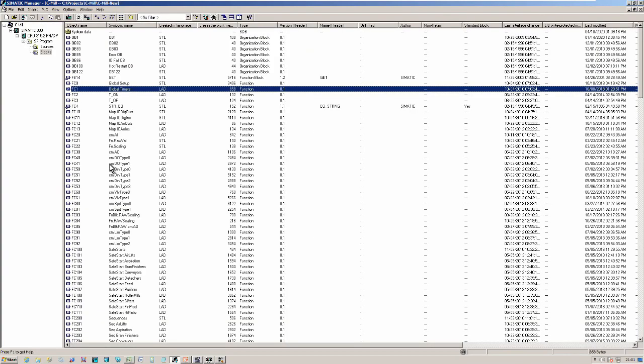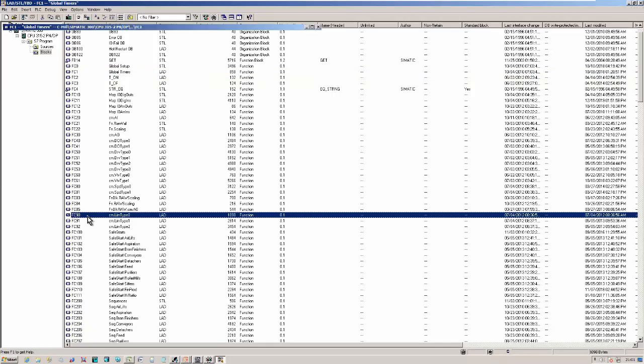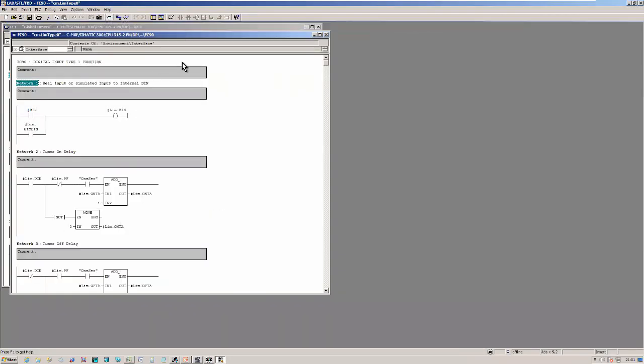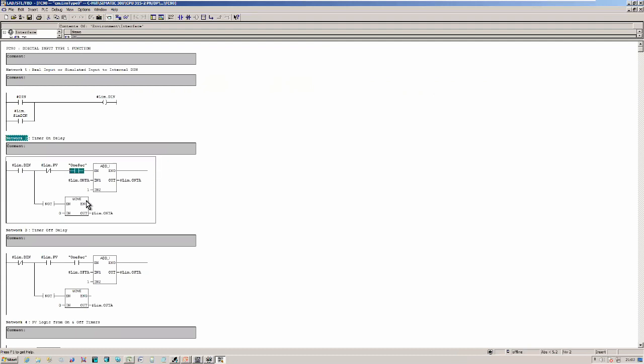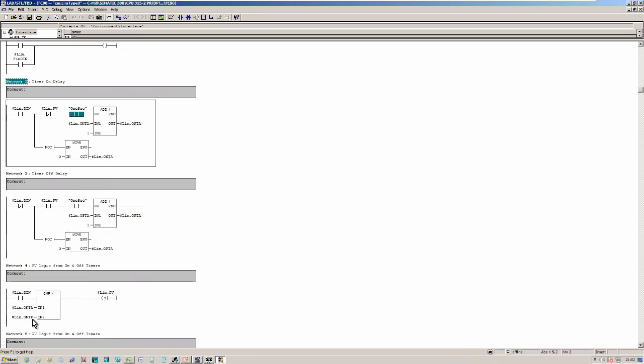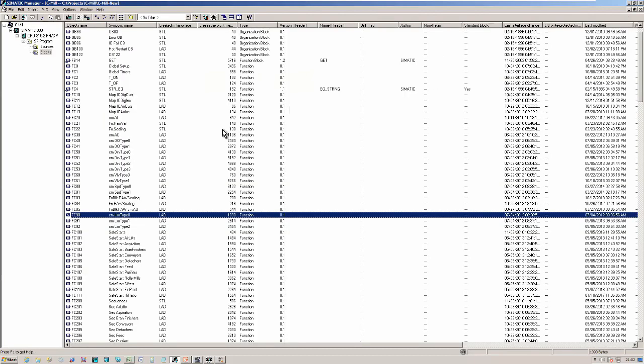If I now go to my digital input block, see there's the 1 sec. It's used everywhere in the program as 1 sec. So if the input is on, every second it will count in this timer, in this block. And when it reaches the preset, it'll put the PV on. That is how we do timers in our programs, but I'll explain that more next time or the following one. Okay, so that is what's important about the clock byte.